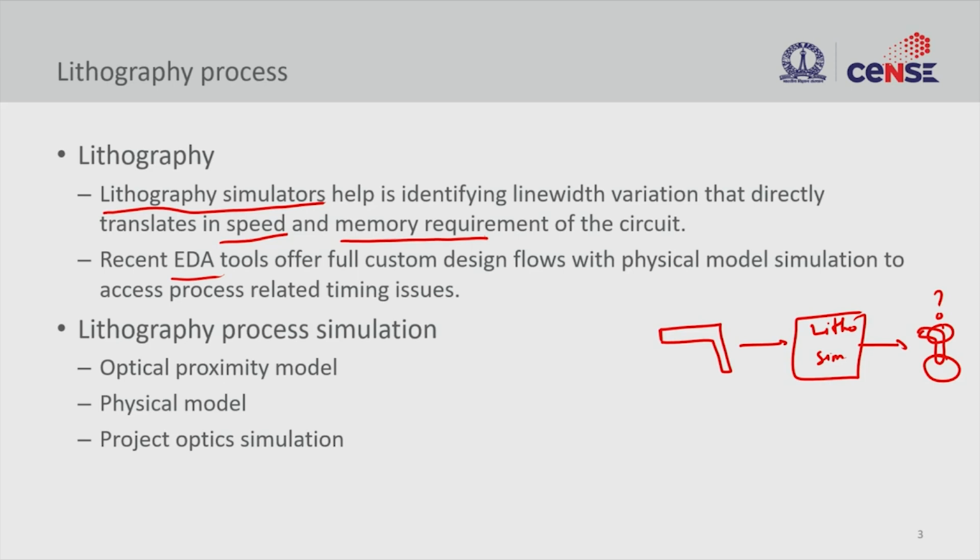If you are doing a digital design and you want to synchronize multiple blocks with a synchronized clock, you may want to have the clocks aligned without any delay between the different blocks. If one block is relatively slower than the other, you might miss the timing, and then all of your logic is going to not meet the requirement, right. So here you want to understand whether my timing will be affected because of the physical design I have, or what is the margin I have. All those things could be done using present-day design tools.